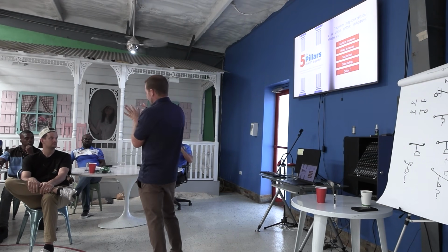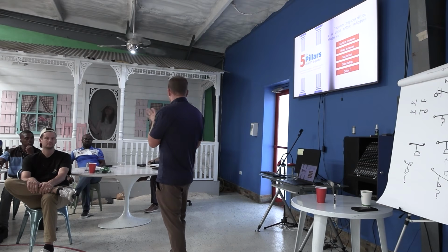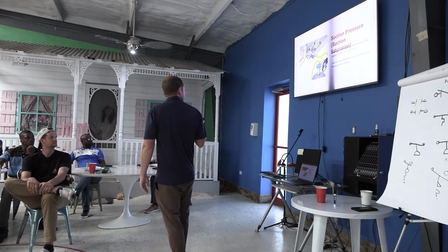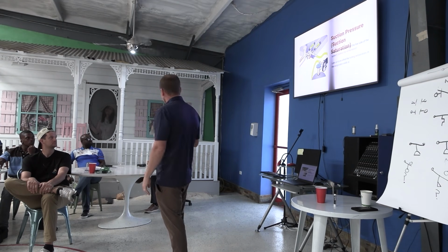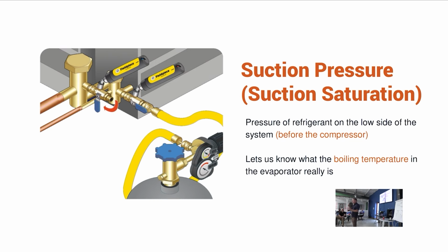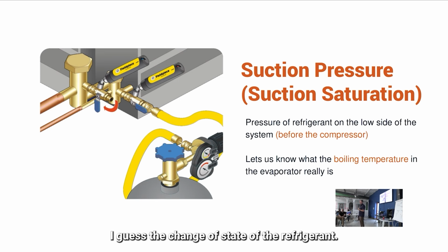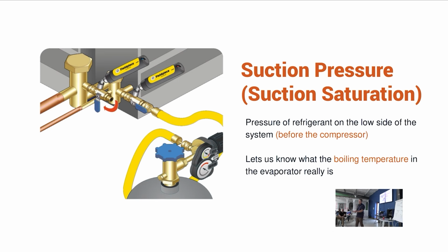But let's talk about what saturated suction temperature means. What does that really signify? I'm going to call on one of you if you don't answer. Romain, what does suction saturation temperature really signify? It's the change of state of the refrigerant. The temperature at which the refrigerant is changing state at that pressure, right?